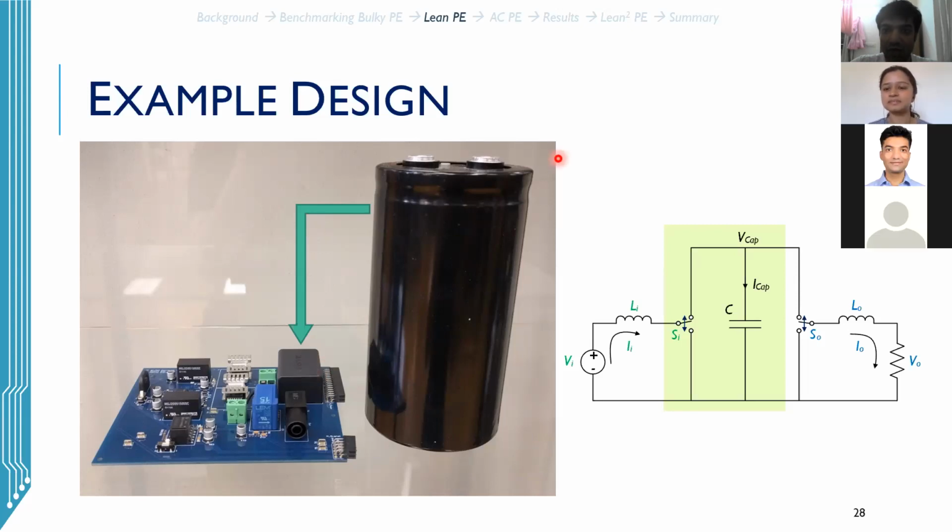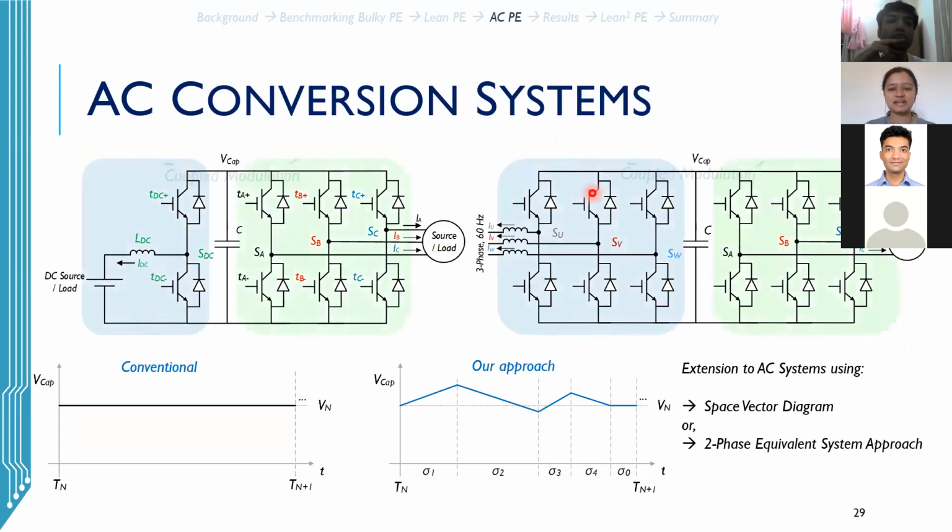Hi, hello. Go ahead, Rishabh. We can hear you. Okay, so since we are reducing the size of capacitors, and I'm talking about photovoltaic application, in photovoltaic application, there is a keen aspect that you should follow maximum power tracking. So since DC link voltage ripple, I don't know how the impact is when we are shifting from a higher size capacitor to a lower size capacitor. I assume the link voltage ripple will increase. So how is it impacting the power point tracking?